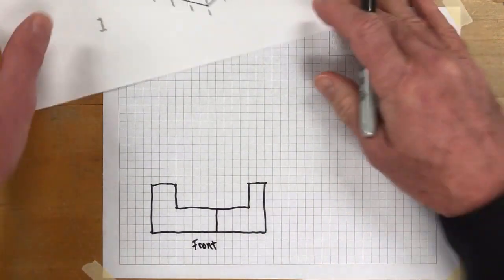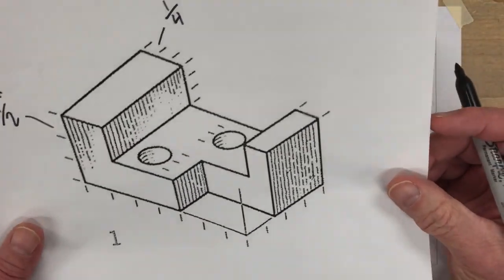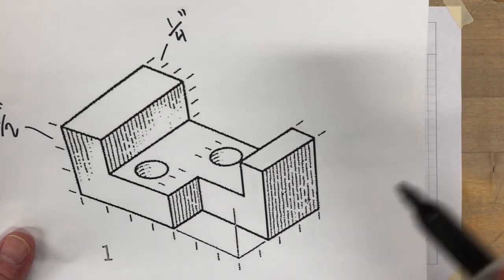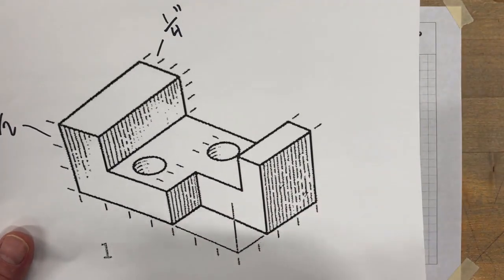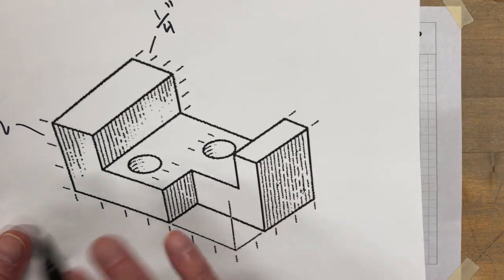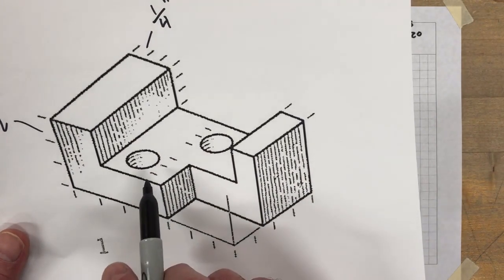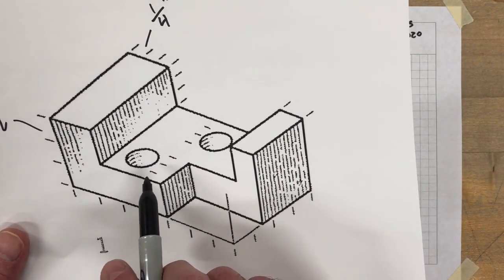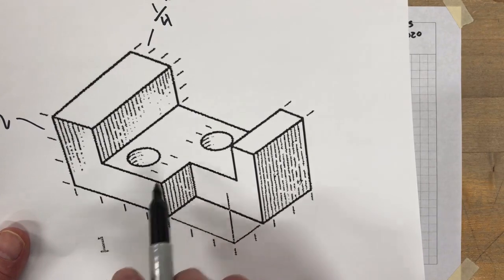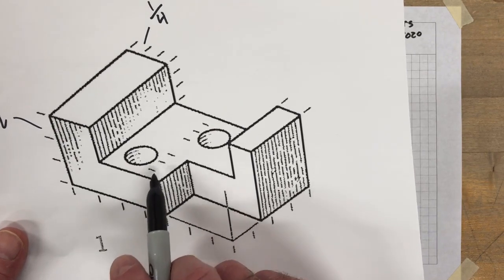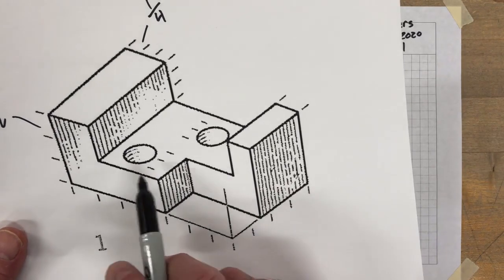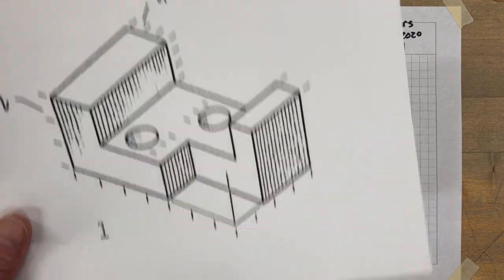Now we're not finished yet because we've got 2 holes in this. Now the holes on this, they're all the way through, that's one thing, and they're either a ½ inch in diameter, about 90% of them are ½ inch in diameter on this particular plate of exercises. So what I need to do is just verify that. Yep, I see 2 small tick marks there, which tells me that these holes are ½ inch in diameter.